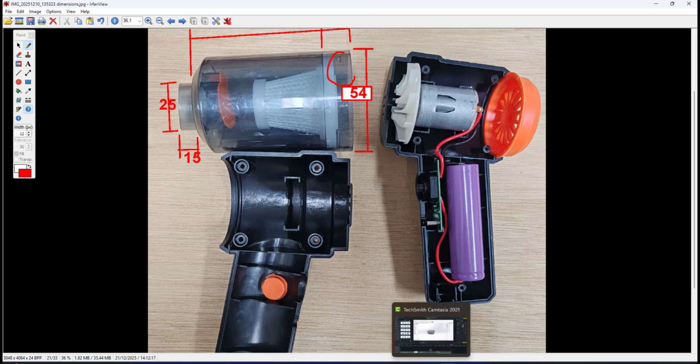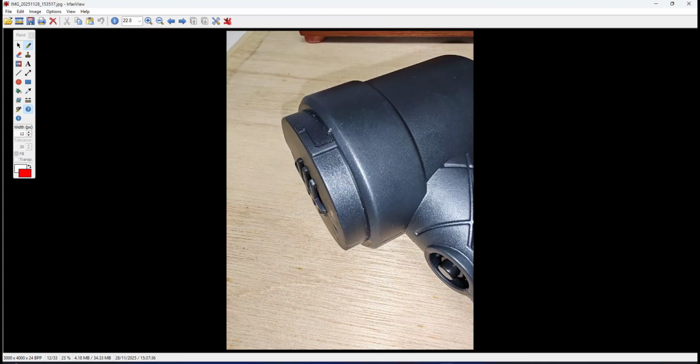If you look at this photo, this is the main body, front and rear casing. I have already shown you how I did this key feature by using the wrap command. When I use the wrap command, this will be embossed to create the key. So the container will be fitted here, which means the container will have the inverse feature, which is the deboss, the cutout.